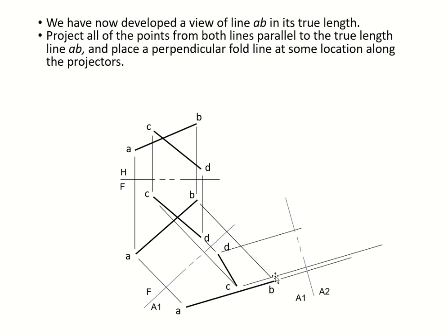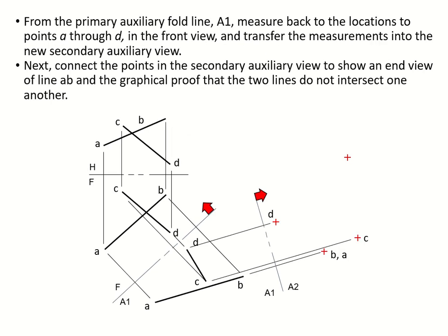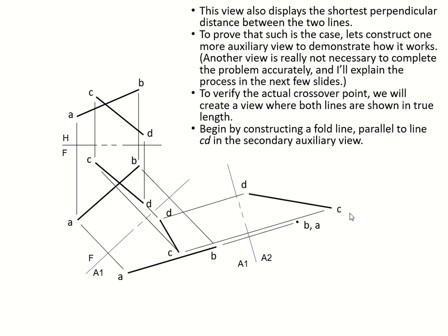We are going to extend again. This line is your edge view, okay? Don't forget it. Extend again, and the third fold line, okay? Direction, our dimension going that direction, so our dimension going this direction for your measure and transfer. We get the points, right, and connect them. So your AB is right here. It's on the same line, so you got A and B, a point. Then you have your CD, okay? This is your fold line in between that two views, so you get D and C.